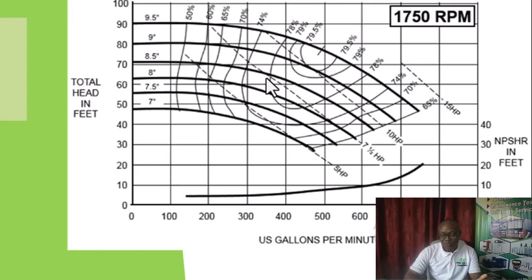That is what will be able to give us that required flow rate and overcome that pressure. Remember too that we have taken something higher, which means that it will work, that is, it will be able to overcome the head that we have calculated earlier, because the 7.5 has a higher head. Are we getting it?